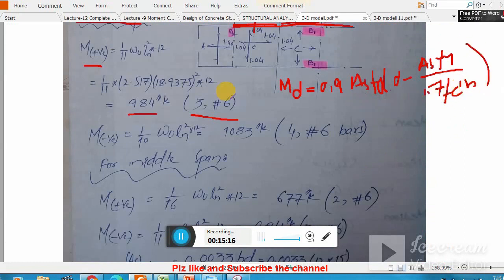Clear? So As is now, if you are providing number 6 bars, your As will be 3 times number 6 bar area, 0.44. So you got the As, just plug the value of As, you know all the values. d is 15 inches and you got the moment capacity, and that moment capacity will be greater than this 984.